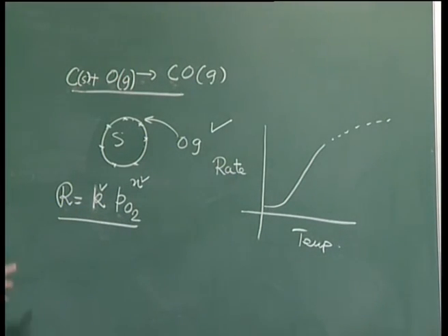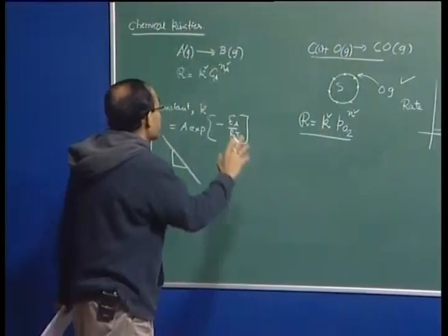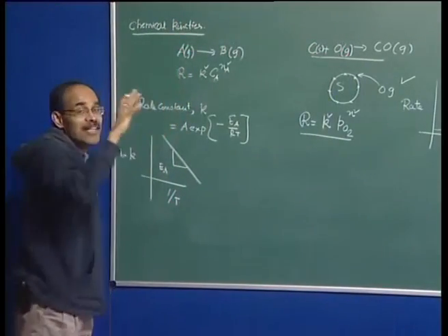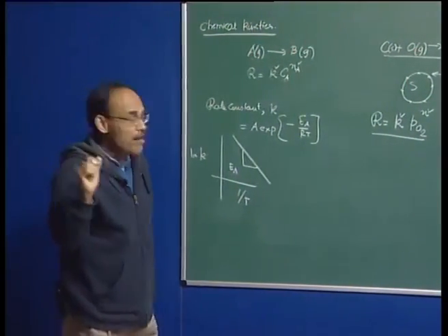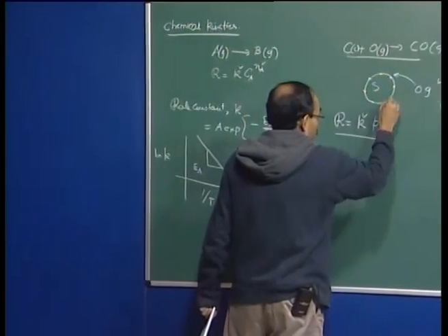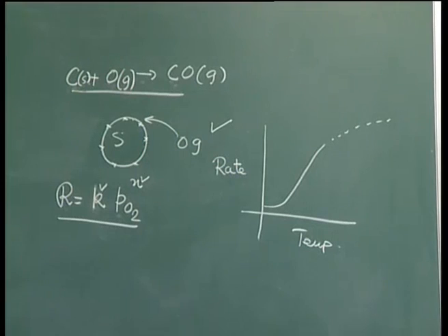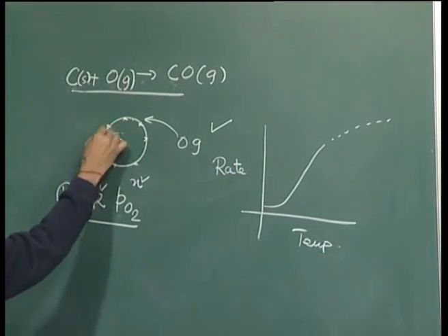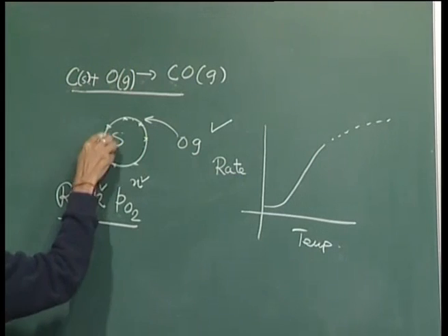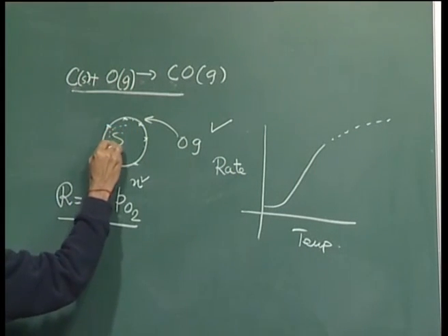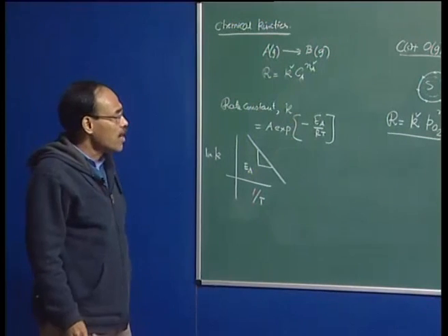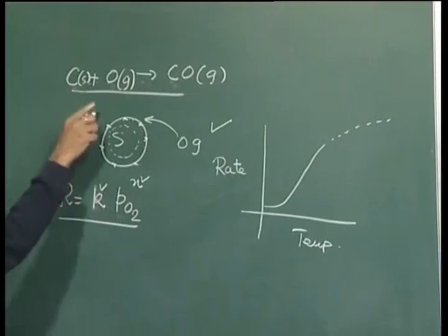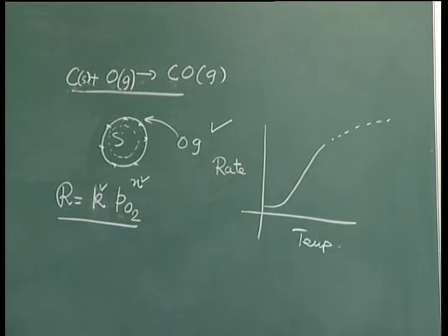So, that shows us that, but it creates some problem in measuring. Specifying the concentration in terms of amount per unit volume is a very easy task. But how do you know the concentration per unit surface, particularly when the reaction front is changing as a function of time? At 10 o'clock, the size of the carbon particle is this, at 10:15 the size of the carbon particle becomes smaller. So, the area is continuously changing. Therefore, there is some problem as far as specifying this concentration at the surface is concerned.